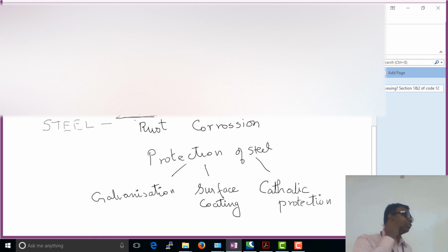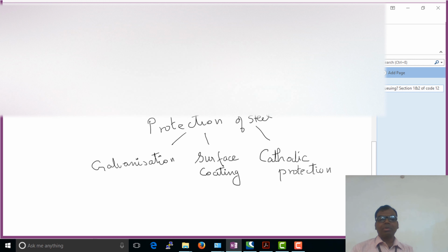So we used to do that a lot. All the steel structures, all the cable trays, all the structures will be kept at equal potential, so that there is no chance of corrosion taking place. So these are some of the ways by which you protect a structure from getting corroded. Now I'll just ask you to recollect, what are the types of corrosion?